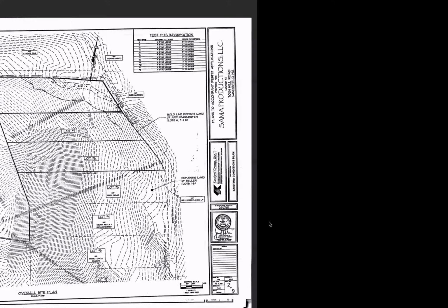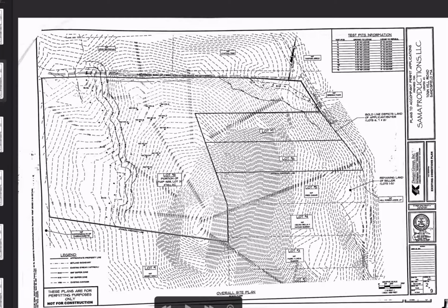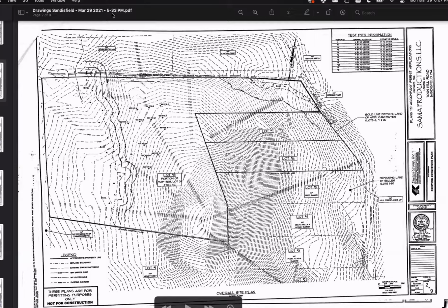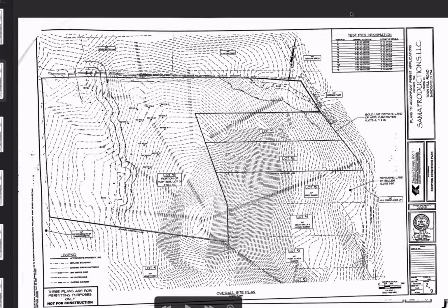That's a darker green color. There's also a finger-like wetland along the road. Our project's 375 feet away from this wetland. Jurisdiction around wetlands is 100 feet. So the project is along the buffer zone in this section. And then the changes that were made are related to stormwater. I've pulled all the stormwater away from the wetlands and redirected it to the upland so that there's no impacts. And the state representative and I had a collaborative discussion.